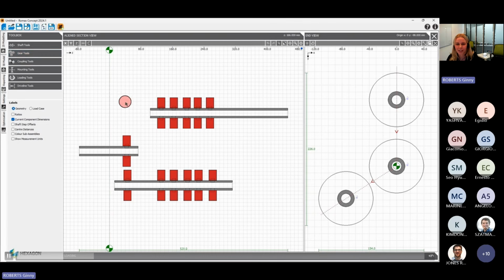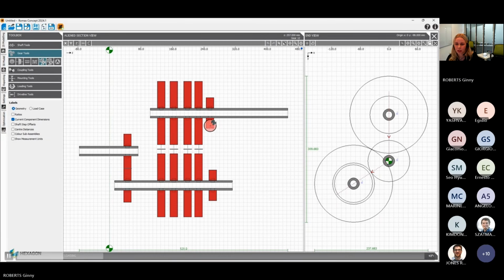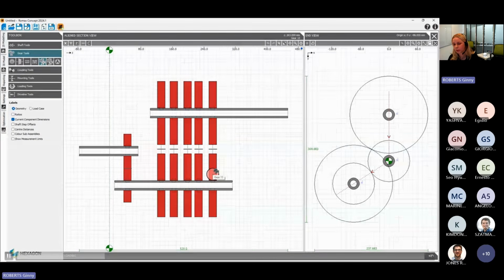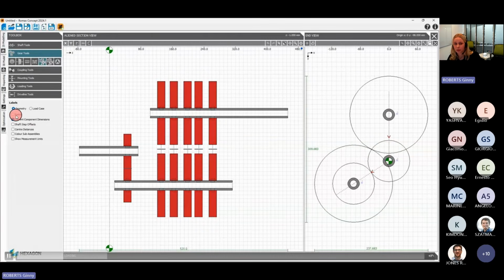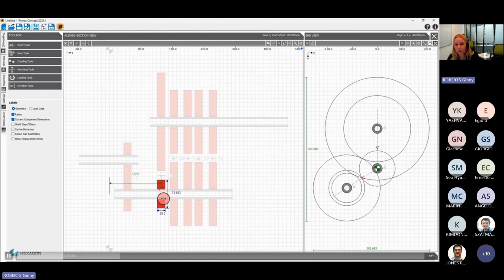I'll just add an extra there, so I'll delete that, and then we can mesh the gear pairs just by clicking on that meshing icon and selecting them one by one. They automatically go to a 1-to-1 ratio, and this ratio is just defined by the circumference of the gears. So for these loading gears, that's the only sort of changeable thing we can do with them at the moment. We can change these ratios either by sliding the gears on the worksheet, or you can just type in the ratios that you want.